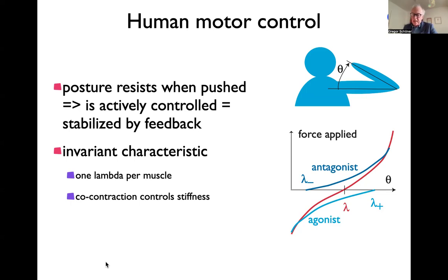So if you don't exactly know where the surface is, for instance, you're just choosing a point inside the surface as your target point, and then as the robot arm hits the surface, it presses against the surface just with that spring constant. And if you make it not too stiff, that table will support that and you will grasp that table. In fact, you can do grasping that way.